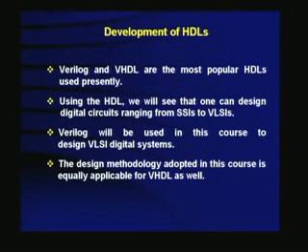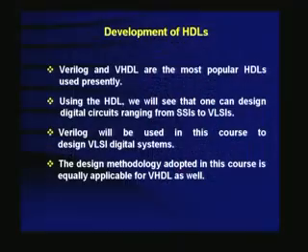There are two types of language. One is called Verilog, the other is VHDL. But we will use Verilog in this course mostly. Verilog and VHDL are the most popular HDLs. Using HDL, we will see that one can design digital circuits all the way from SSI, small scale integrated circuits like gates and a simple one bit full adder, to VLSI ICs like microprocessors. Verilog will be used in this course, not VHDL. There is a subtle difference in the way in which you do things. Verilog is more industry friendly, VHDL is used in academics, and in some parts of the world they use Verilog, other parts VHDL. It doesn't matter really.